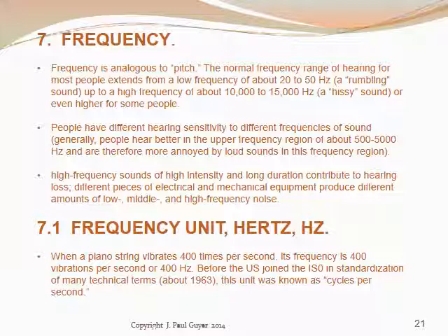High-frequency sounds of high intensity and long duration contribute to hearing loss. Different pieces of electrical and mechanical equipment produce different amounts of low, middle, and high-frequency noise, and noise control materials and treatments vary in their effectiveness as a function of frequency. Usually, low-frequency noise is more difficult to control. Most treatments perform better at high frequency.